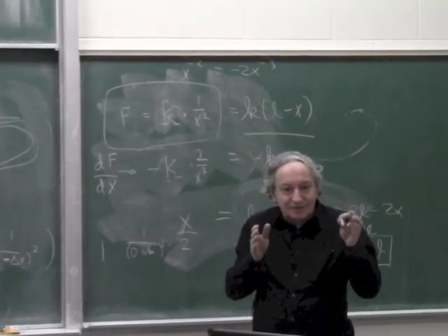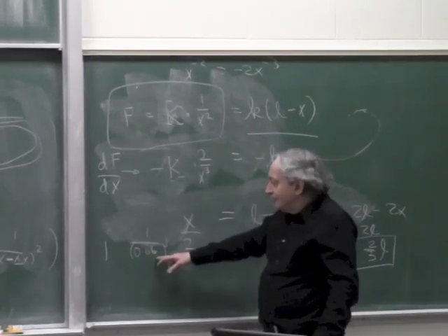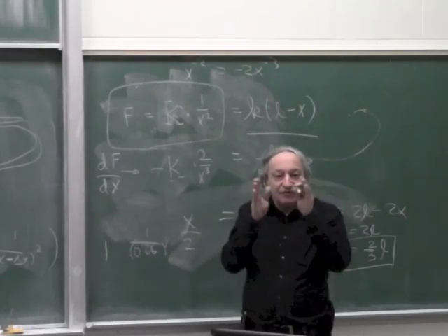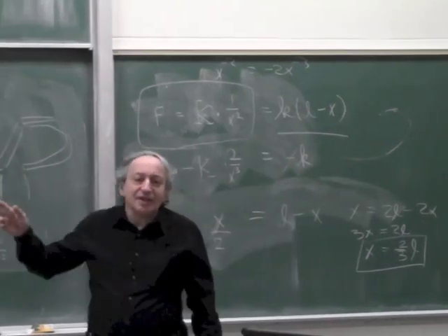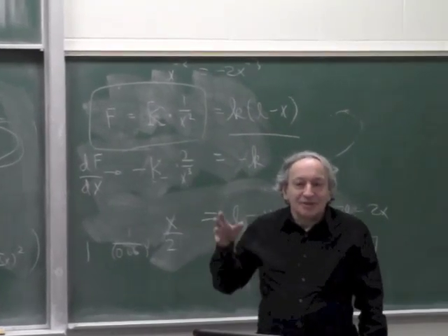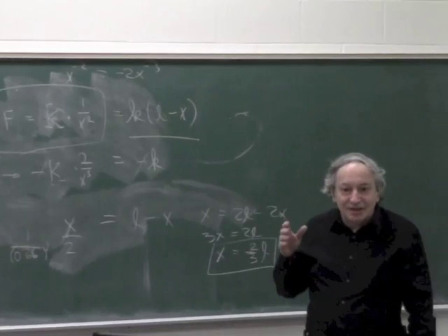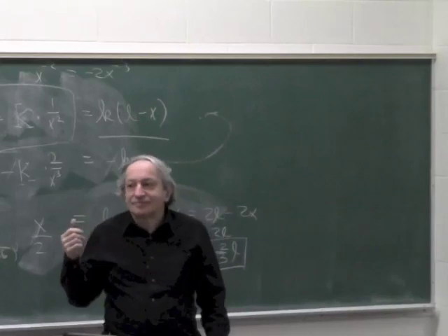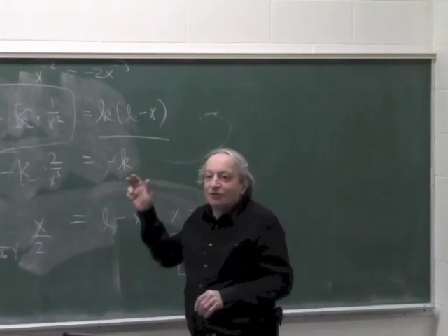Even over that third, the gain will change a lot. Because this is 2/3, okay, 1 over this, say roughly, is 50%, so the gain will change from 1 to half, or from 1 to 2, even over that 1/3 of the motion. So this explains why non-linear actuators are not used much in servo, although they're cheap and simple and don't need sealing and don't demagnetize. They have every possible advantage, but they have one killer disadvantage, that their gain changes and they snap. Okay, clear? Good.